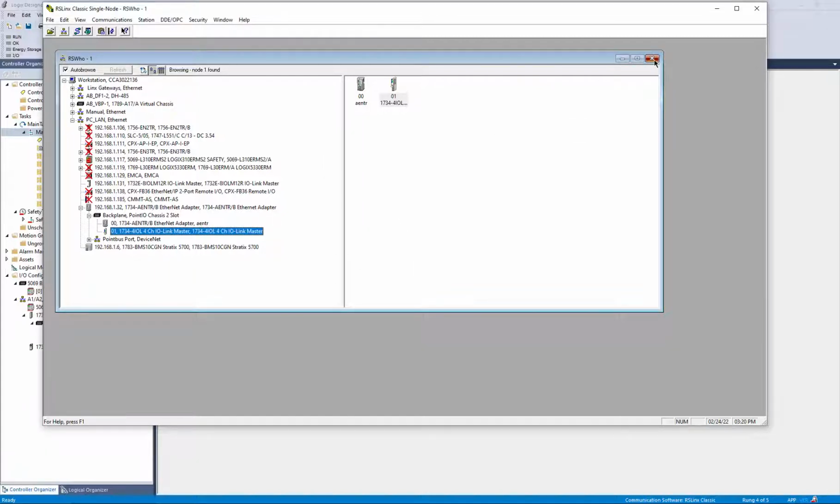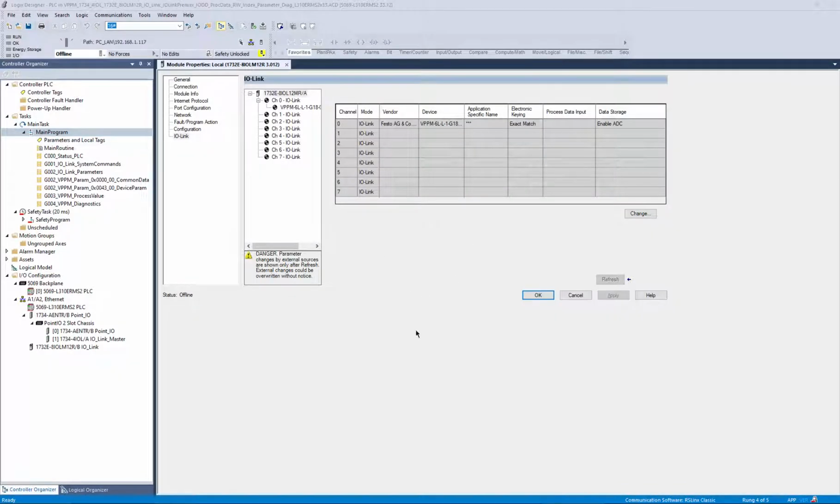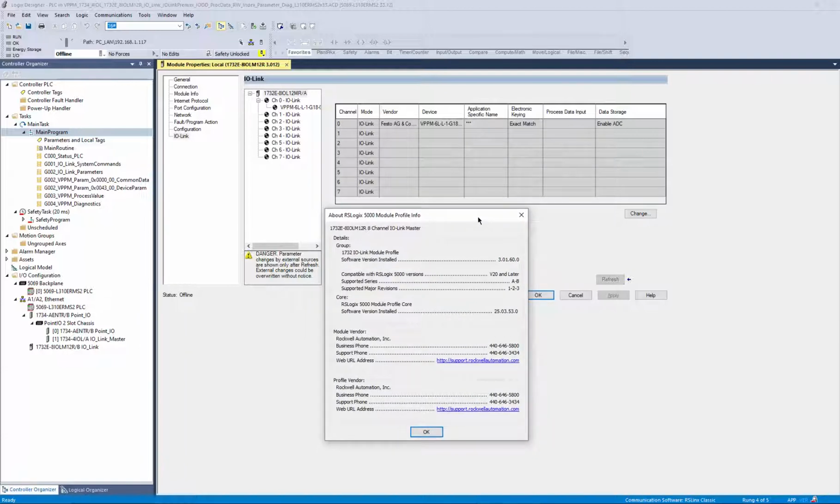The next point is add-on profile. So if you go to the Festo website, or not the Festo website, the Rockwell website, you can download what's called AOPs or add-on profiles, and it's important to match the profile. So make sure that the module profile is compatible to the firmware and at the same time compatible with what you want to have happen, like as far as the data storage goes.